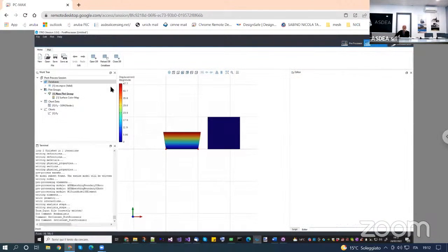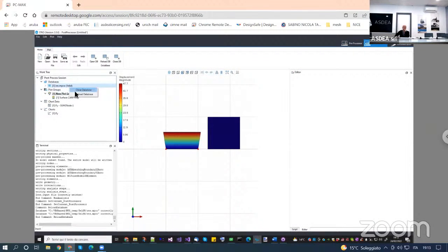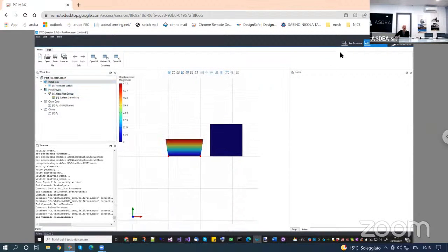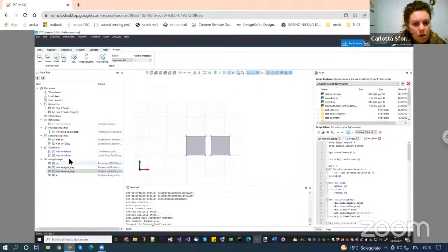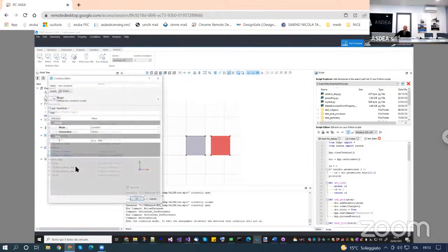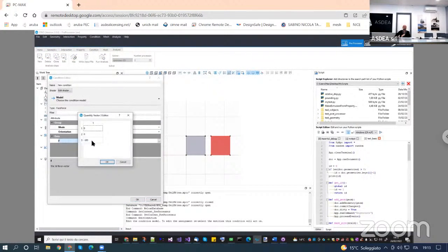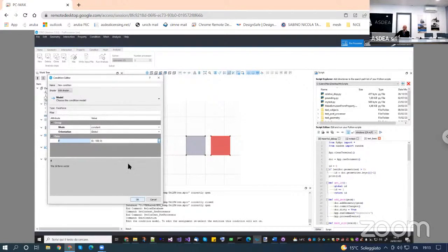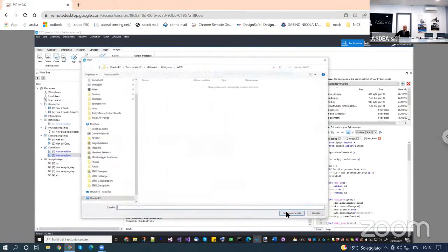Let's go back to the results. Reload. Okay, something here. Let me see why. Phase force condition is applied here. Oh, yeah, my mistake. Look here, where did they put it? In the Z direction. But when I am in 2D, it should actually be in the Y direction, because I have only 2 dimensions. Okay, run the analysis again.